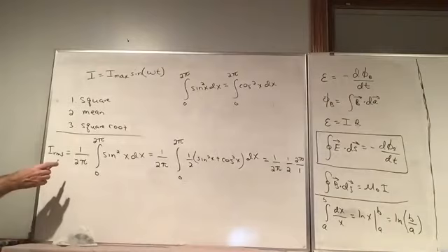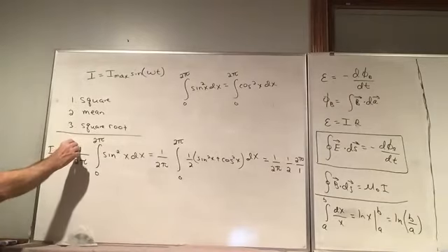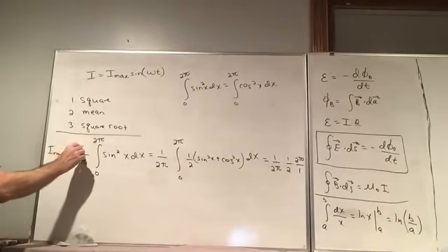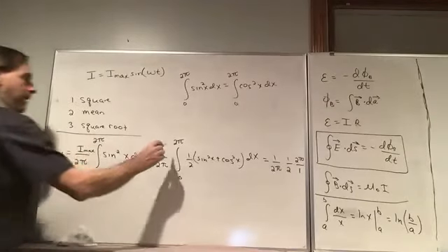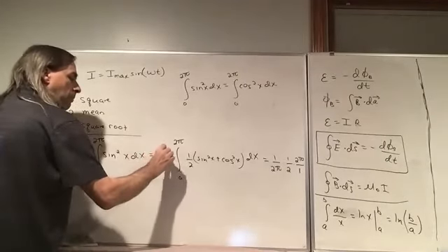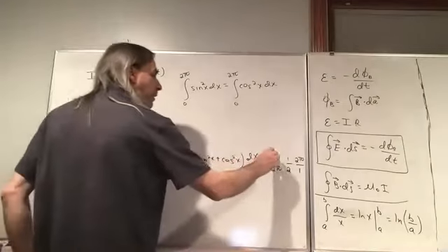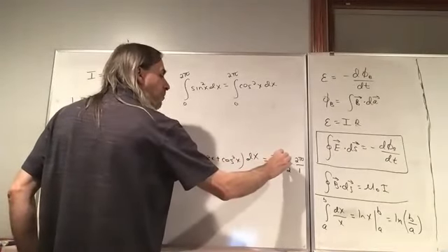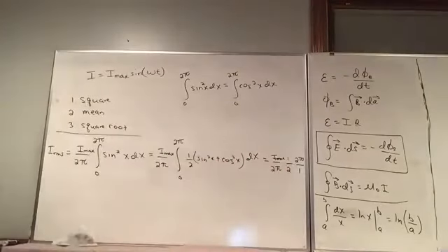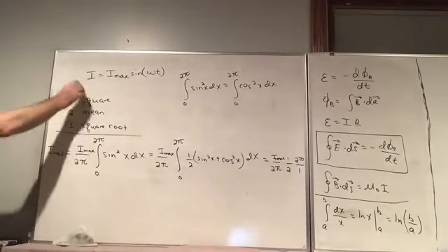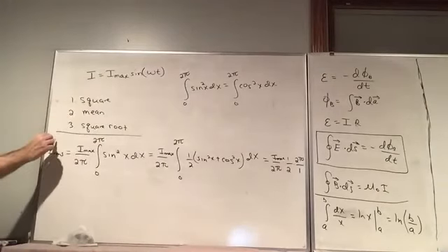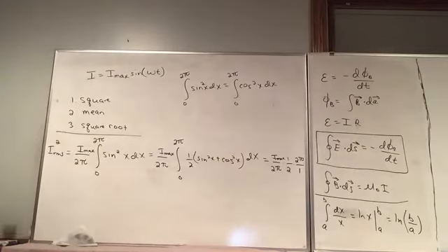Sorry, I forgot I max everywhere. I was just looking at the sine part, but I wrote I RMS, so we take the average of I RMS squared.